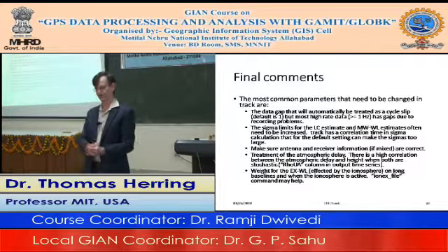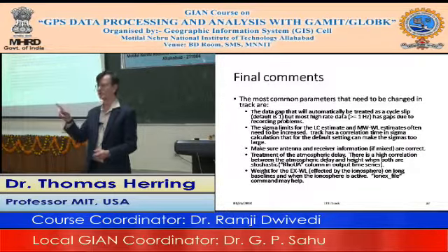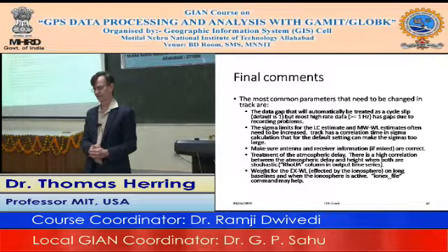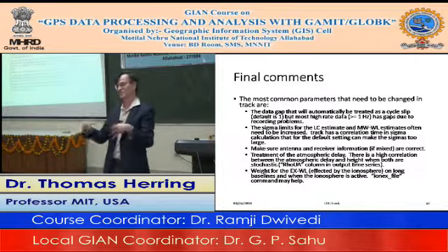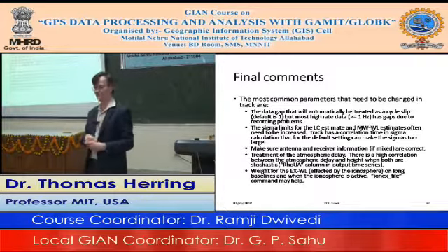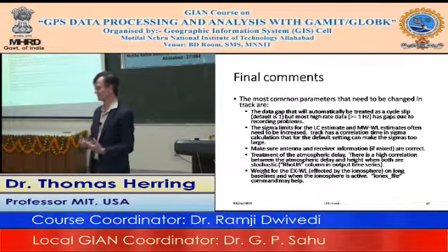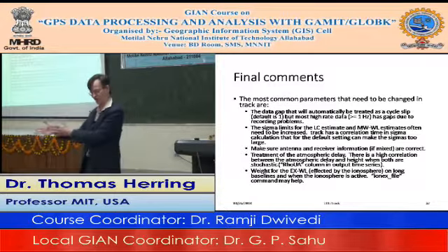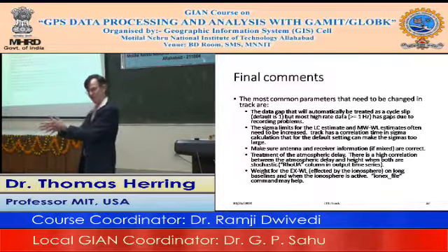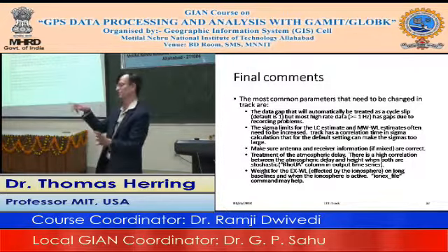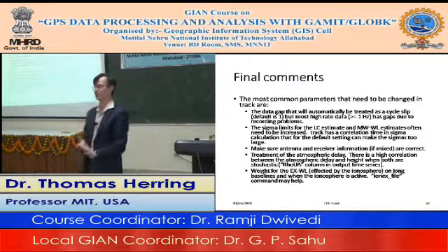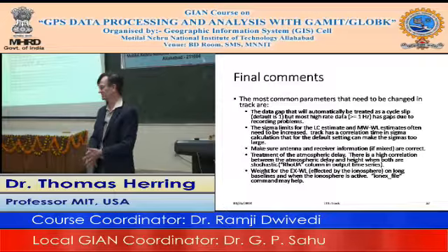You could look at the local site that's near here that's not your site, the LCK. How about 20, 30, 40 kilometers away? No, it is around 90 kilometers from Kanpur, from where the other receivers were. So 90 kilometers, that's a good kinematic size. And you will start seeing the impacts of multipath and things like that when you do this. If you do kinematic positioning every day, that same 4-minute shift that you see in the phase residual, you will often see that same 4-minute shift in the position estimates as a function of time. So if you wanted to play around, that's probably a good baseline to play around with initially.